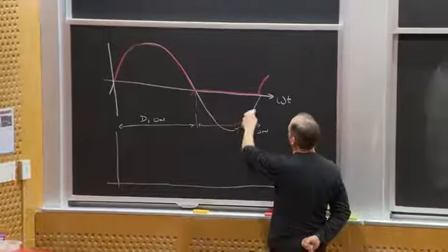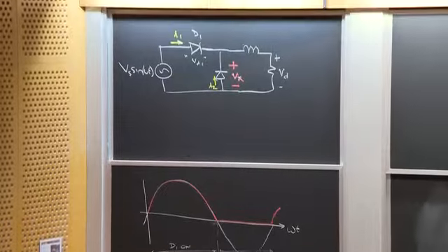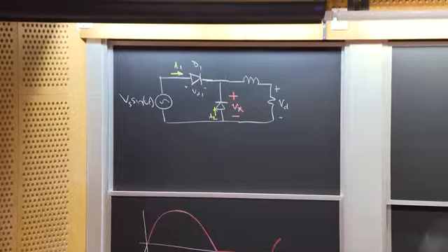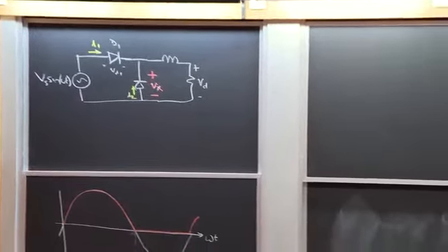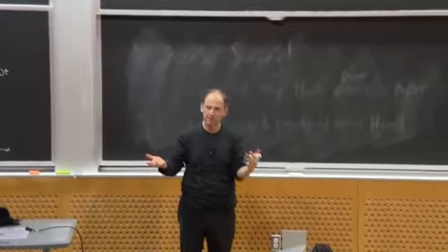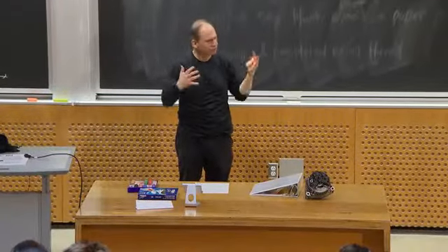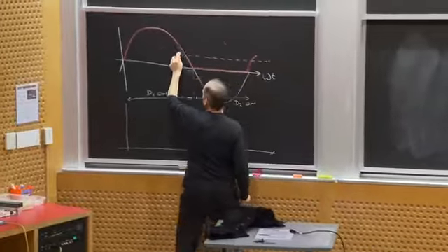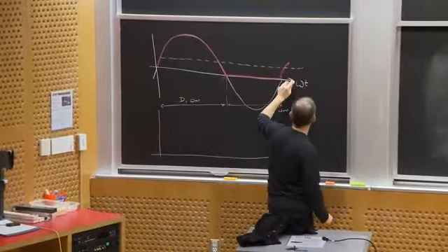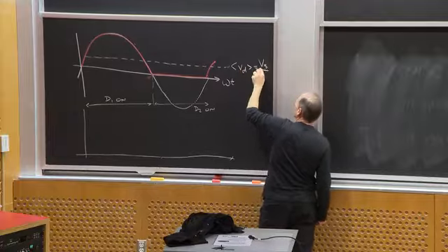And then we went further to say, okay, what is the output voltage VD? And what we did was by basically saying the average voltage across that inductor has to be 0 in periodic steady state. We know that the average voltage of Vx is the average voltage VD. If I assume that inductor is really big and the ripple current in it's really small, the output voltage is roughly constant, and the value it's going to take on, by analyzing that, we said the average value of VD is simply going to be equal to Vs over pi.